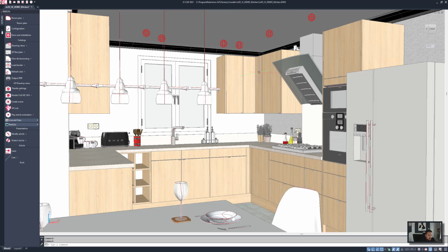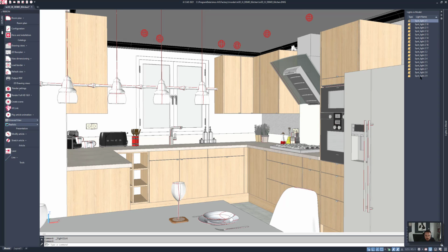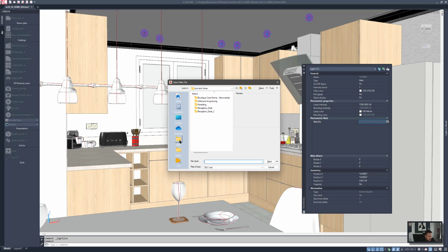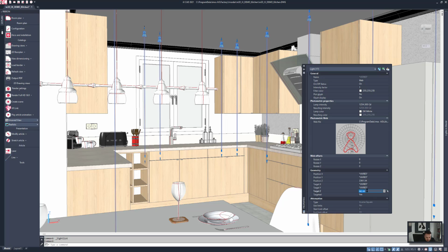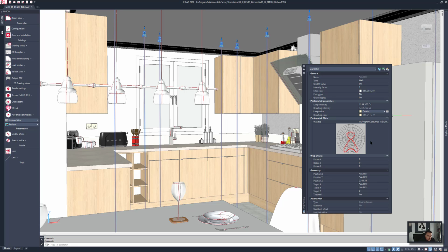So I need to make a couple of changes to the light settings. So we have settings over here now in the new version where we can come into render settings and then go to the light lists. And then over here, all of my lights, I can go to the properties and specify that this is using real world lighting. So we'll go to the spotlights. We can say that these are targeted and the target should be on the floor. We also want to maybe change these to be a quartz style light, and we also then want to change our other render settings.